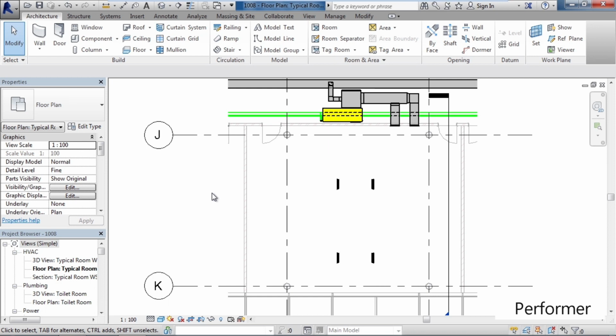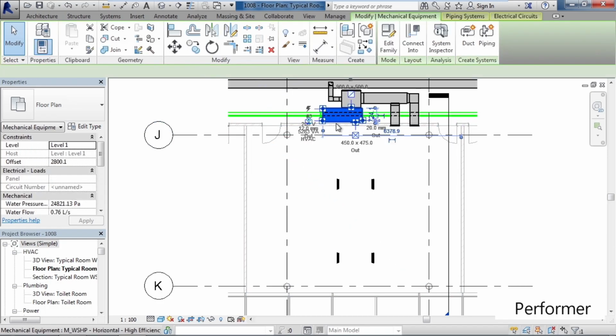So to get started with this, the first thing you would do is create your actual starting point of some duct components. Once you have a few duct components placed, you can create the duct system. That step process would be to first click one of these elements. So I'm going to start where the air would be supplied at and choose the actual mechanical equipment supplying the air.